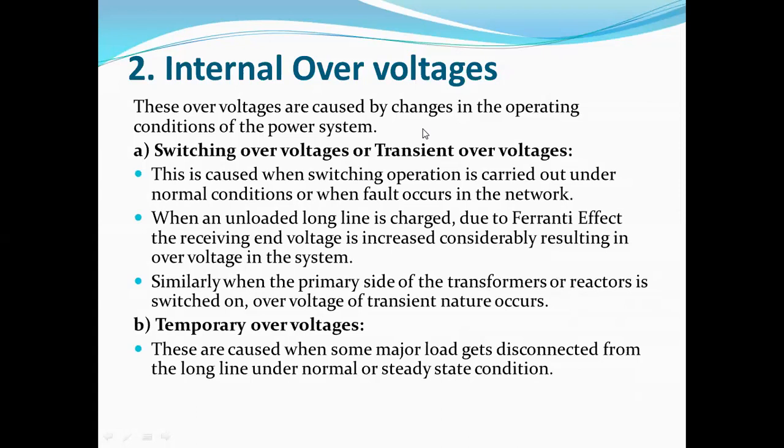We are supplying only as required. So when that load gets disconnected from that long line, under normal or steady state condition, then again the voltage will increase. So these are the causes of over voltages: first is the external and second is the internal.